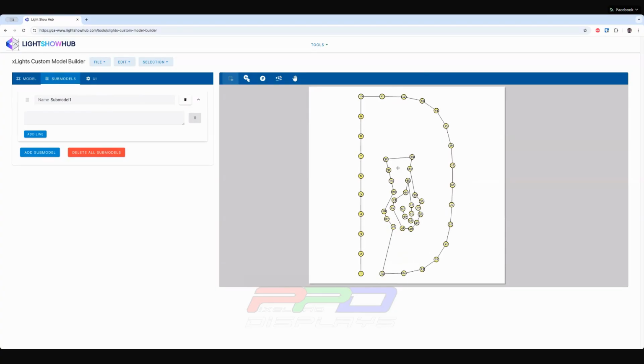And the header that is included in SVGs is typically wrong. It's typically used in points, even though it'll say inches, and it's not. So it's very interesting. That's why I add it there as an option, because it is A, wrong with SVGs, and B, typically not included for DXF.